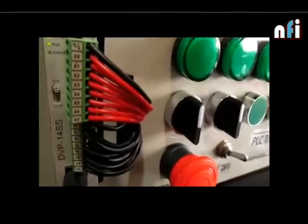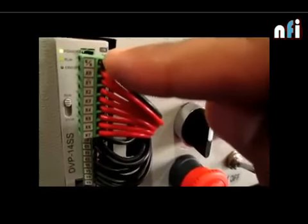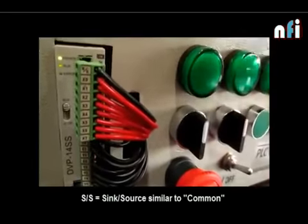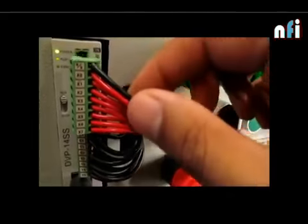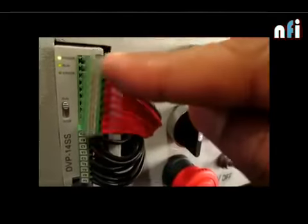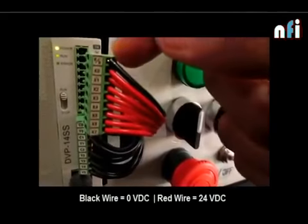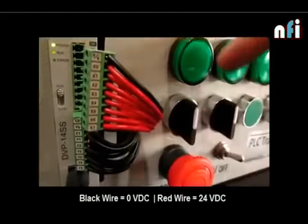Now as you have studied in the automation diagram, we have a common, but here we have S/S, sync source. So this is just a different term we are using here, but generally it's the common port of all these inputs, SS. Now this black wire indicates we have given 0 volt to the sync source, and this red wire indicates we are getting 24 volt outputs from all these buttons to this PLC. So let me connect it again.